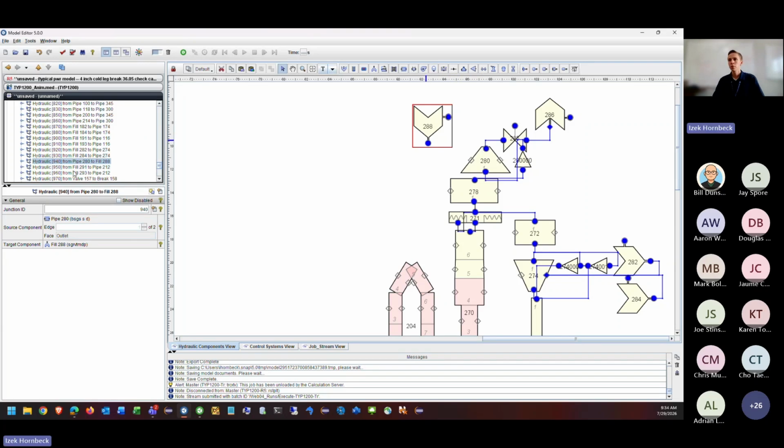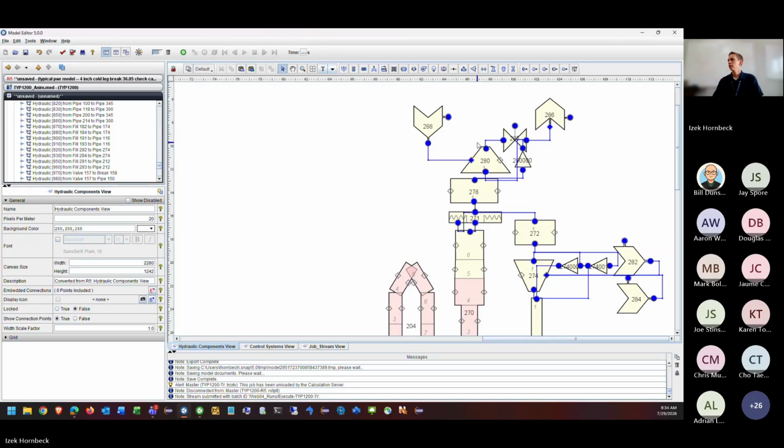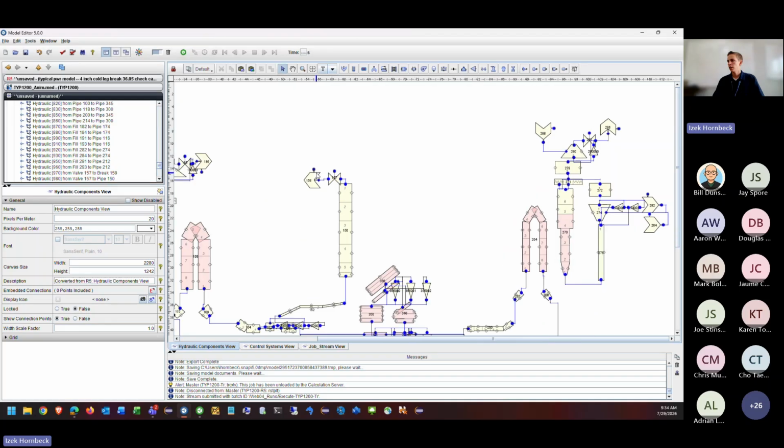So we'll remove this connection and just do the same thing. We'll disconnect that, manually connect the fill to the pipe, and then change our angle here to 180 to say that we're actually connected to that outlet right there. So we have those straightened out.